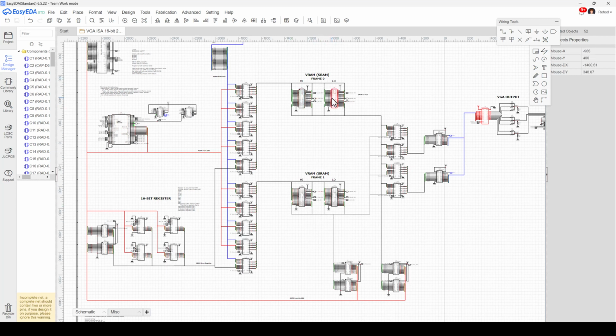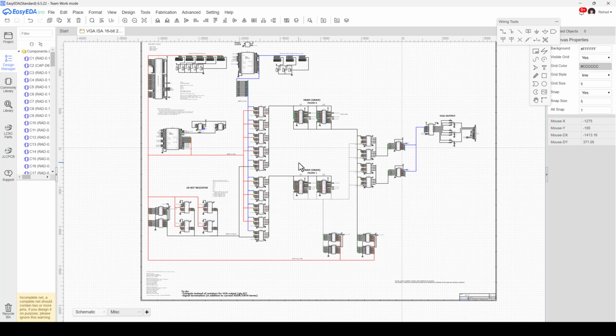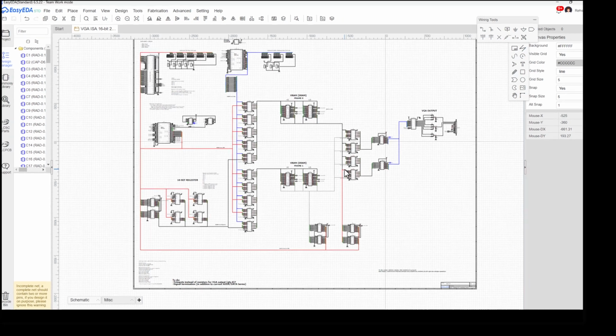I've got a meg and I'm only using half a meg. So I could go to 2 bytes of color data per pixel, still fit it into everything here pretty nicely, and really have minimal changes other than taking out a pair of these transceivers. But I'll maybe come to that later. For now, 8 bits is plenty for what I'm trying to do, but that is some flexibility I have down the road.